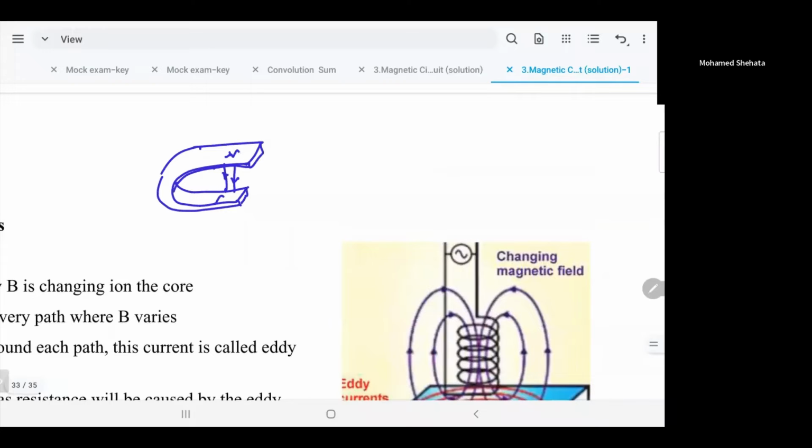We have a magnetic field fixed, not changing with time, and you have a conductor. This conductor, let's say, is connected to something that can measure any voltage. So if you leave the conductor not moving and the magnet not moving, nothing will happen in the galvanometer, it will be at zero. Zero EMF is produced. If you move the conductor, shake the conductor, then you will find the galvanometer, or whatever measuring instrument you're using, will detect induced EMF voltage. And if it's closed, then the current will go through this loop.